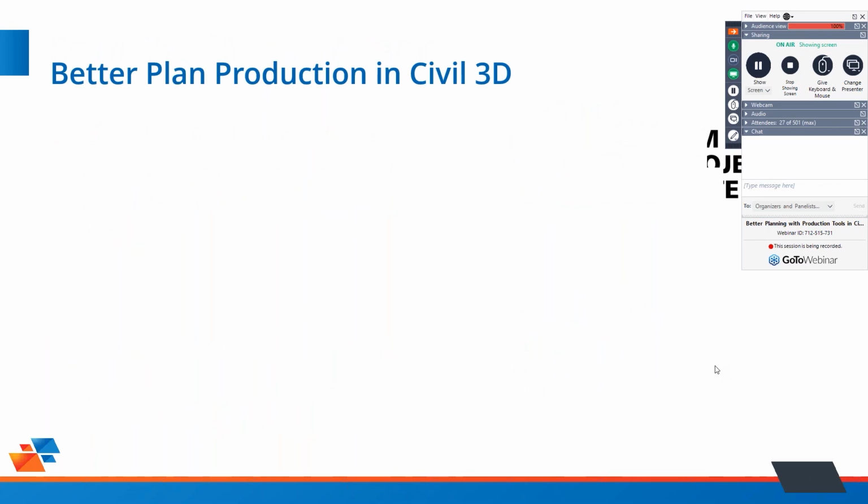We want to show you better plan production tools than you're used to in Civil 3D. While there's some great stuff in there, a lot of it's pretty painful, and you guys spend a ton of time in plan production. I want to show you one tool set that creates dynamic plan and profile sheets. There's a native tool set in Civil 3D that will create plan and profile sheets or plan and plan, but once the sheets are made, they're just kind of on their own.